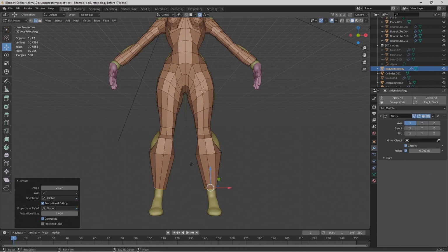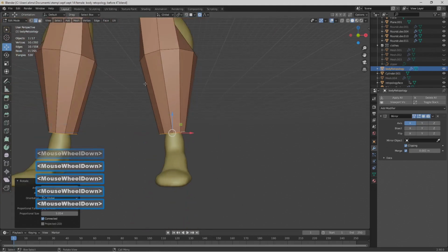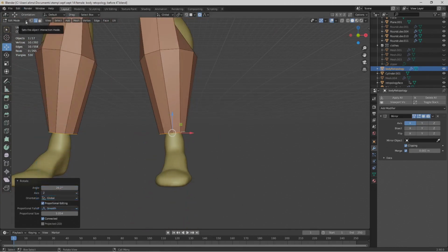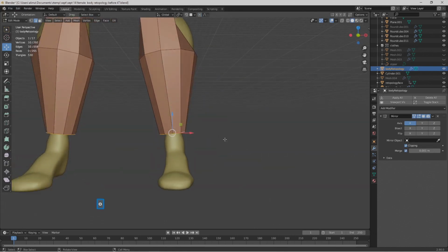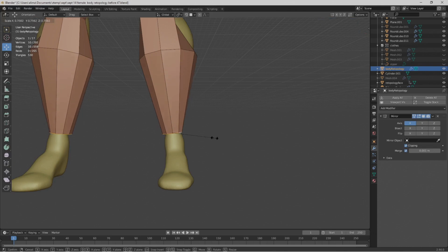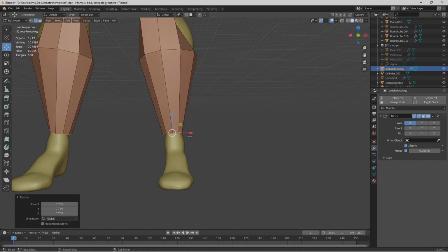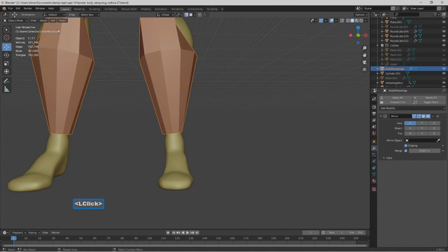Okay, I'm going to hold Shift, press B, draw a zoom box to zoom in here. Actually, let's make this smaller while we have this selected. I'm going to press O to turn off the proportional editing tool. Press S to make this smaller, this being that edge loop there. I'm going to go to the upper left, go to object mode, turn on snapping, come back to the upper left, go back to edit mode.